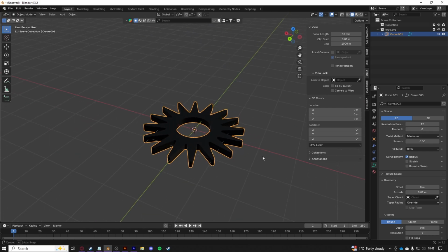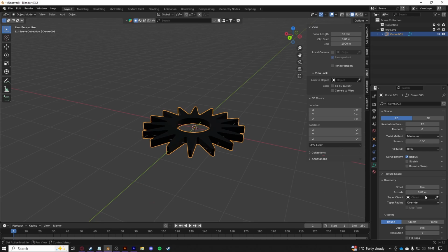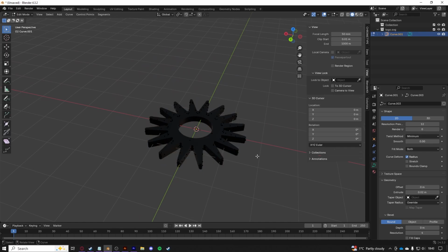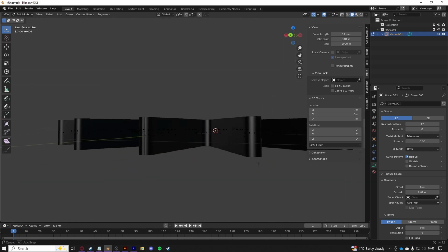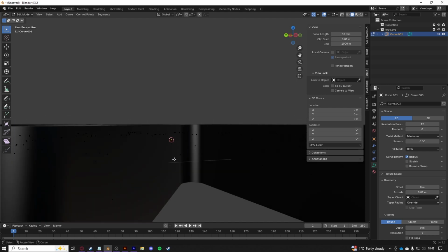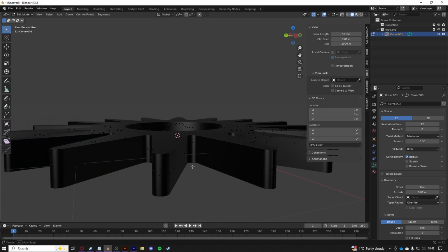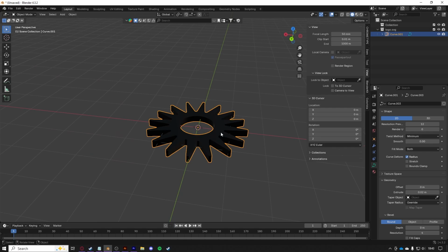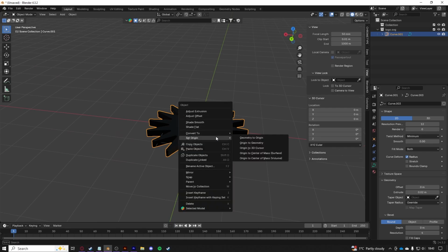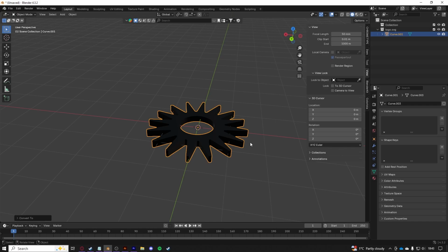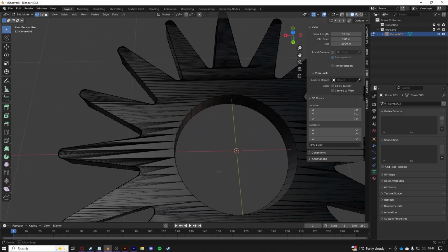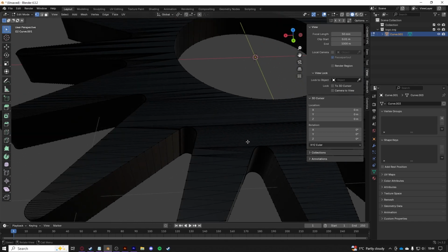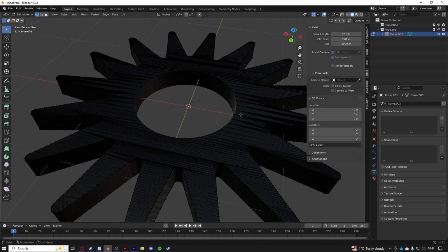To begin with, we're going to want to make it a mesh, which is basically like finalising the options here. Because if we take a look at this object in edit mode right now, and press Tab, it looks like this. It's still flat. You see the vertices. So if we press Tab to go back to object mode, we're going to right click it, and we're going to go to Convert to Mesh. Now if we press Tab to go back into edit mode, the topology looks terrible. Like, what is that? That's an absolute mess. It should really look gridded, and I'm going to show you how to fix that.